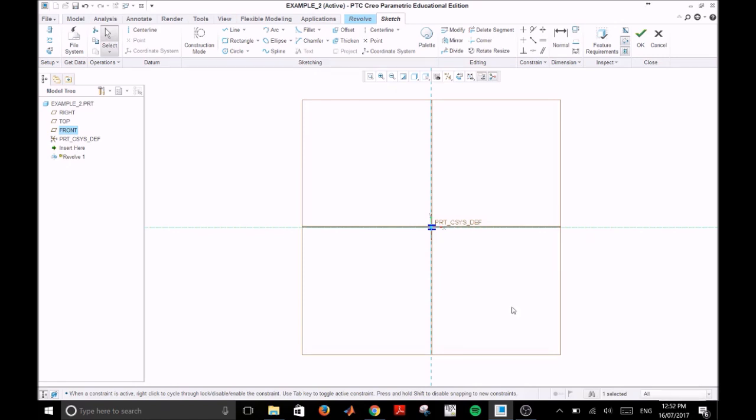Now we can create sketches as per the extrusion video by selecting a rectangle, clicking the location of the vertices, and middle clicking to complete. Note that Creo has put in two weak dimensions that we can click and drag to make visible, and these are referenced as a diameter, which is a much easier way of working when we're doing revolutions. We can now create strong dimensions by double clicking this length, typing in 200 mm.